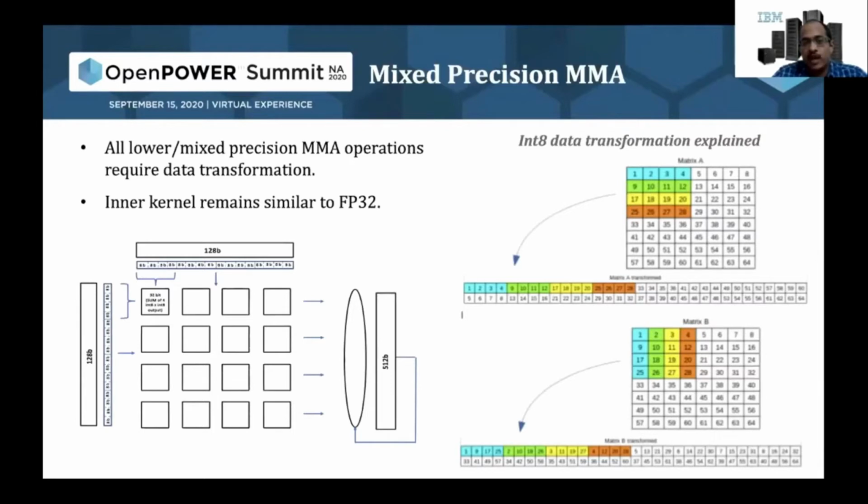To achieve the same, and as described previously, the ISA performs internal multiply accumulations within a subset and then accumulates the partial result to a bigger set. A simple transformation for an int8 matrix multiplication is explained in the figure at the right hand side. Similar transformation operations can be performed for int4, which extends to include 8 elements within a subset, and for int16 and half precision, this gets reduced to 2 elements in a subset.